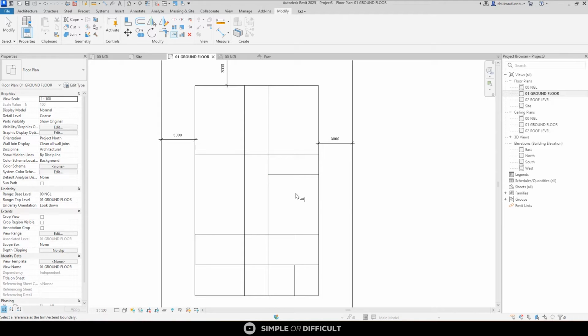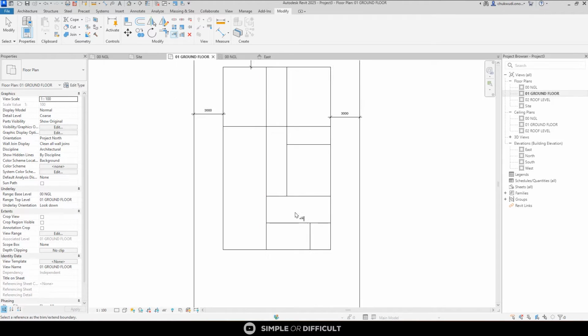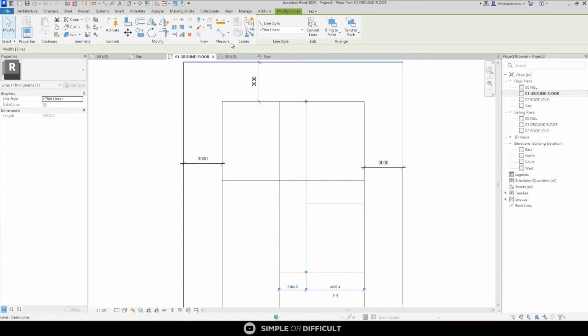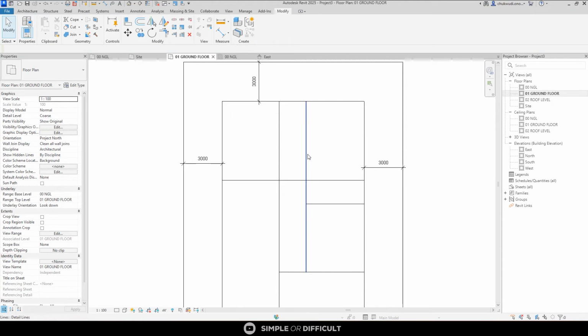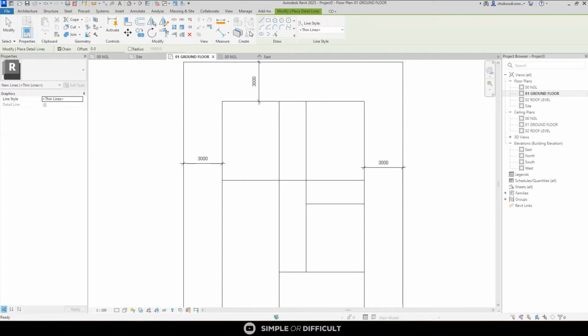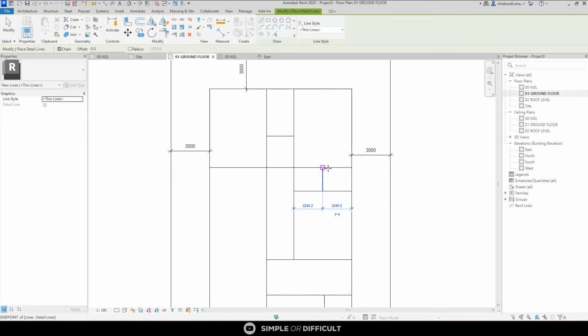It is going to take it back. I want to bring this one back to this place. The same thing I will do over there, this one like this, and even this one too. So now let me create similar. You can right click and you see Create Similar over here, or you can use this icon here, which is also Create Similar. Let me terminate this over here, and maybe terminate this one over here too, because we're going to have the bathroom and the wardrobe over there.